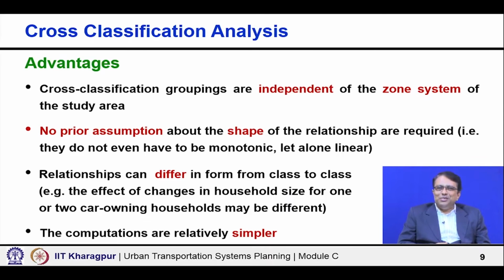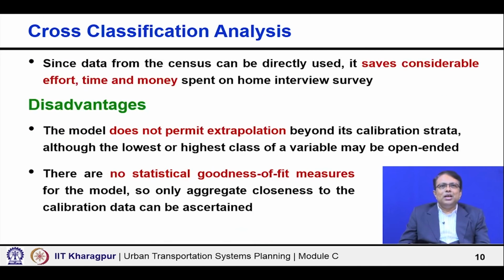You simply get so many households, you need only them to be statistically representative. So many households making so many trips. The total trips divided by the total number of households under the category gives the rate. Same thing is true in the context of trip attraction rates. So, the methodology is very simple.